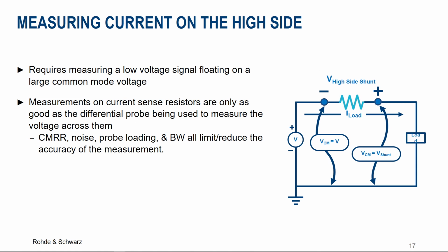So when you're trying to measure the current, especially on the high side, many designers turn to a sense resistor instead of a current probe because the inductance from the wire loop often perturbs the circuit. Often there's already a resistor in the design in series between the gate driver and the gate. To minimize the insertion impedance in the circuit under test, the resistance of the sense resistor is kept very small, which means that the voltage drop across the sense resistor will also be very small.